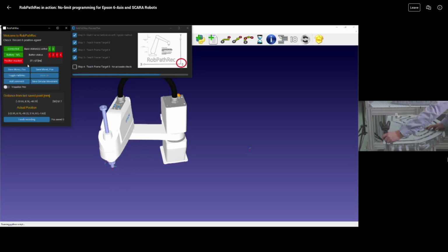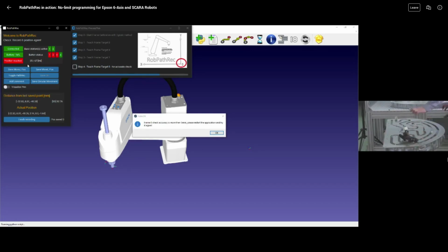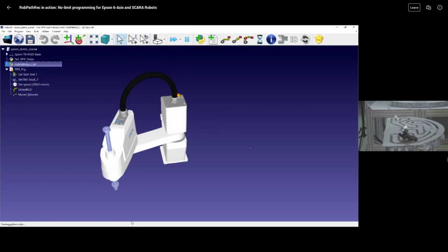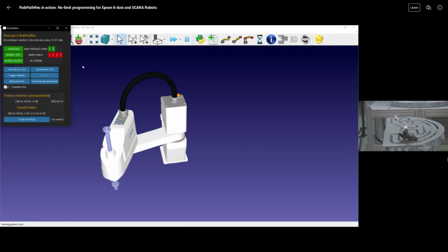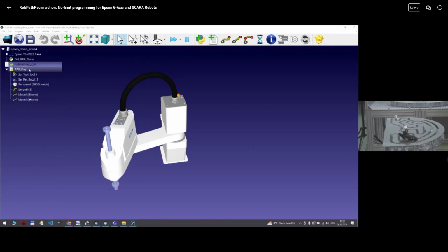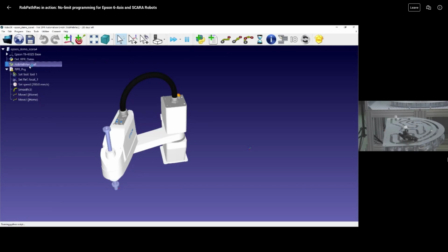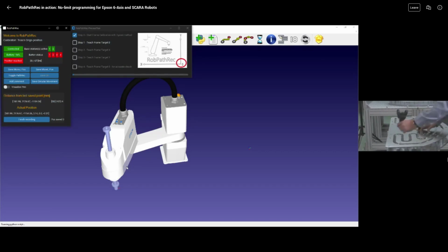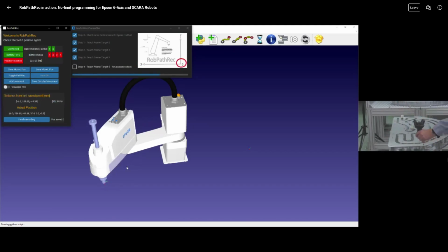And then you will see if the accuracy is good enough or not. In this case, just like we would have planned this, this was above 5 millimeter. This is very important in our opinion, because if the accuracy is not even 5 millimeter, then we want to tell it to our user that the accuracy will be not as good as it was expected. Balázs just repeats the calibration, and this is the reason behind why the calibration should be done before each run.